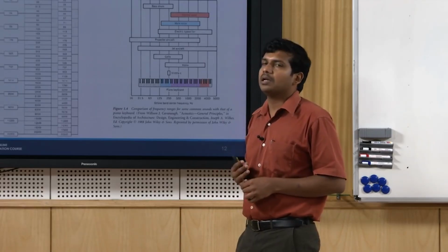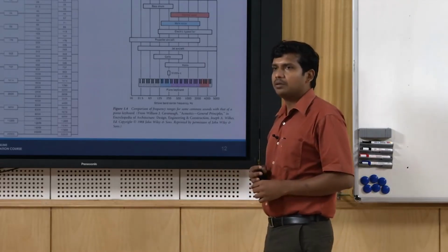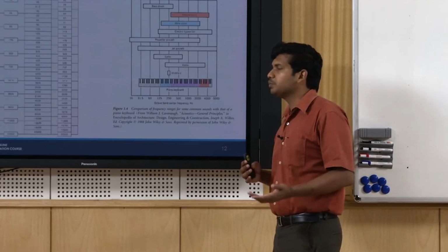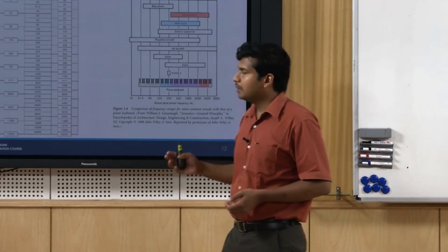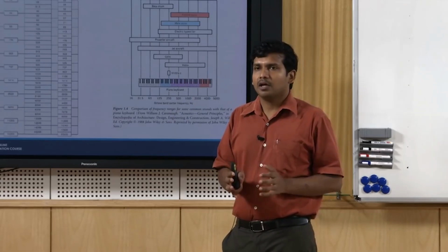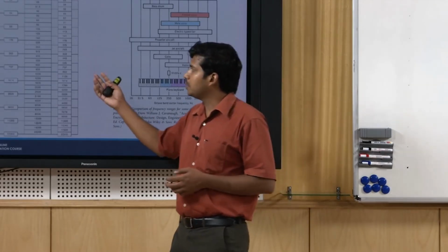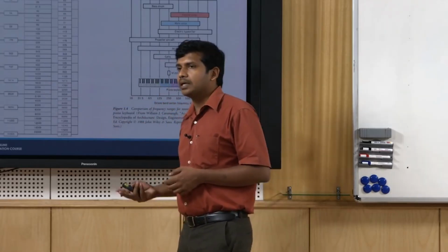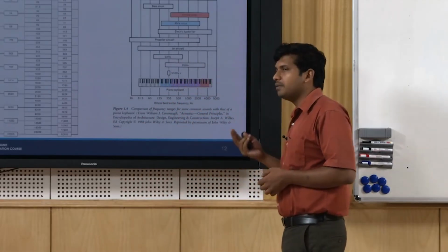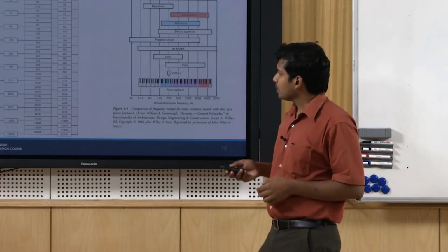Similarly for environmental noise, if you want to design a noise barrier, arrest the sound, or do soundproofing, the first idea you should have is about the sound pressure level, how intense the sound is, and number 2, in which frequency spectrum the sound is getting emitted. If you know these two characteristics, then you will be able to effectively contain or treat the sound source.